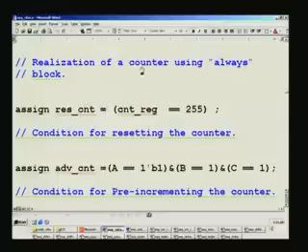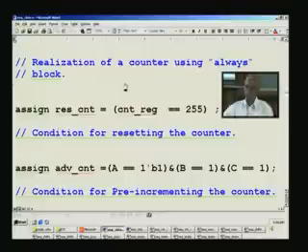I have just put some 50 megahertz, 20 nanosecond is the time period. So that works out to be 1000 by 20. Always divide 1000 by 20, you will straight away get megahertz. So that works out to be 50. So 50 megahertz is a typical value on an FPGA, and that is the reason why I stuck to that.